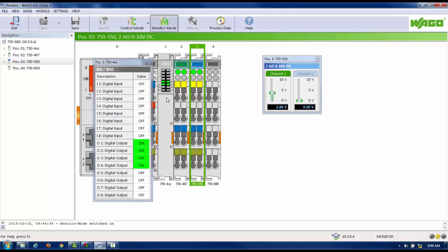And then you can see as I'm toggling the values here, it's toggling those outputs here on the output card, the digital input output card. Now I had that reset that would reset this value here. So I go high, and of course it's reset this value here based on the program, again running in the master device. And as soon as I turn off my reset, my count starts going up again as far as my voltage level here.